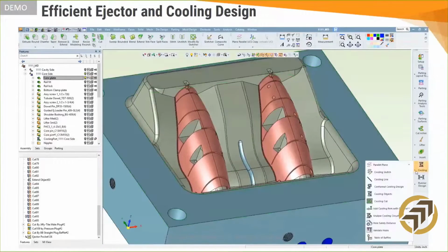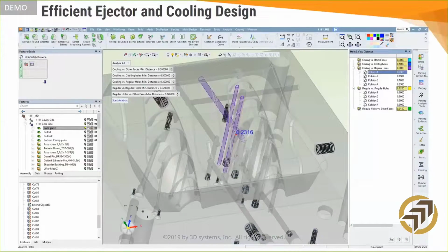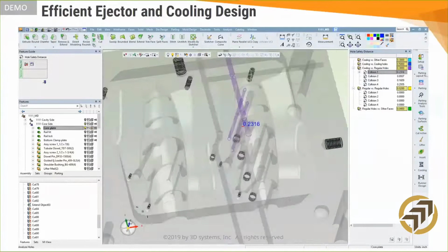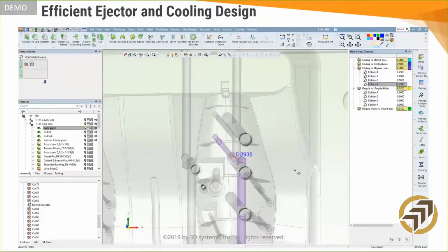Despite the best efforts of software automation, some checks for design errors are always worth the time to run. To help analyze all of the holes that a mold design sees, we've created a tool to check the various safe distances that you deem acceptable. In analysis, 5 different checks are made between cooling channels, part faces, and drilled holes of other types. Every instance that falls under the safe distance is reported and illustrated on screen so that corrections can be made as needed.